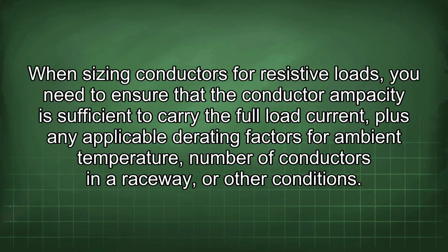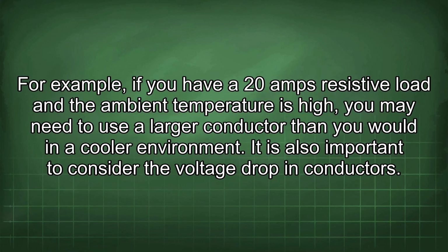When sizing conductors for resistive loads, you need to ensure that the conductor ampacity is sufficient to carry the full load current, plus any applicable derating factors for ambient temperature, number of conductors in a raceway, or other conditions. For example, if you have a 20 amps resistive load and the ambient temperature is high, you may need to use a larger conductor than you would in a cooler environment.